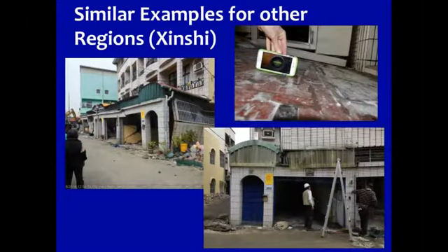Here, similar examples from other regions, and we mentioned at the beginning 3 distinct regions, Jiun-Wei being another. You see the perspective view of a tall 3-story residential building. And in each of these cases, hints of structural damage in the background due to significant relative displacement of isolated footing elements that support, in this case, carports, exterior carports, and hardscapes within those carports. You can see the manifestation of large strains induced on the lightweight components of these buildings due to the surrounding ground failure.